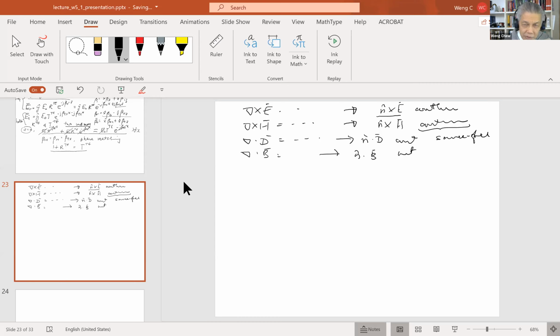I would have chosen the first two because the first two boundary conditions have more substance in them. It says tangential E is continuous. There are two components of tangential E field. Tangential H is continuous. There are two components of tangential H. Normal D is continuous, only one component there. Okay, so these two boundary conditions are not as rich as the first two.